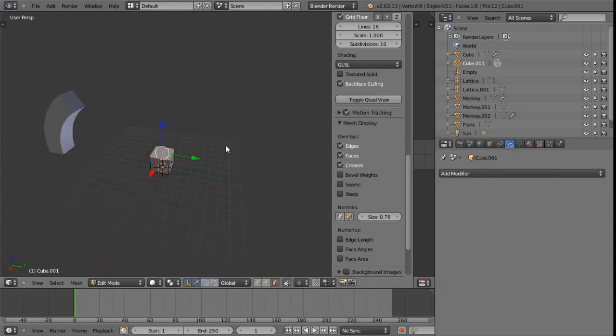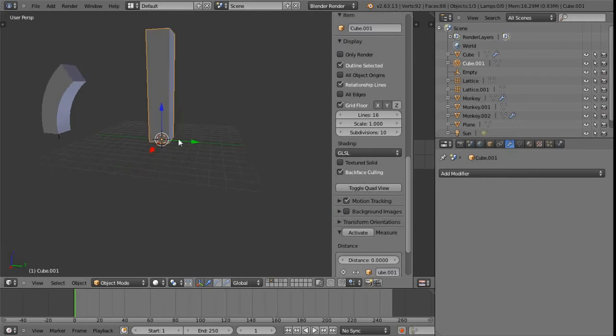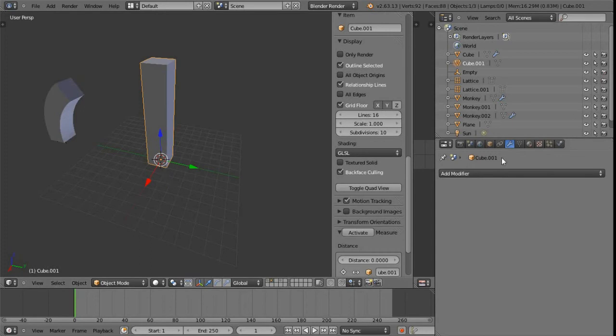Let's grab this top face and just move it straight up. Just going to press Ctrl R and now scroll the wheel to increase the divisions there, and now press left click to confirm that. Now press tab back out, and that should do it for this simple, elongated cube that we've got.